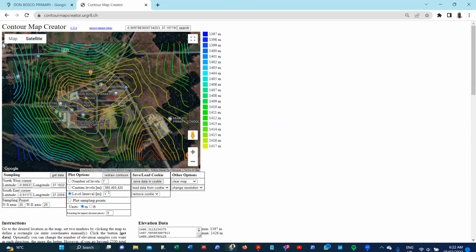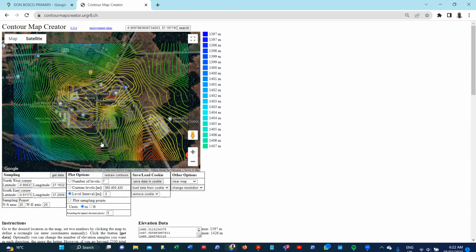That's a contour interval of 1 meter, okay? And you can now clearly see there's a pattern, okay? And we can clearly pick what we'll call the highest areas of our site, okay? For me, I will advise you to, so that you have a detailed model, given a chance, I'll push it to even 0.5. What you'll notice is that it will double our contours, okay? When it's doubled, the better, okay? So that you have a lot of clarity in terms of your site.